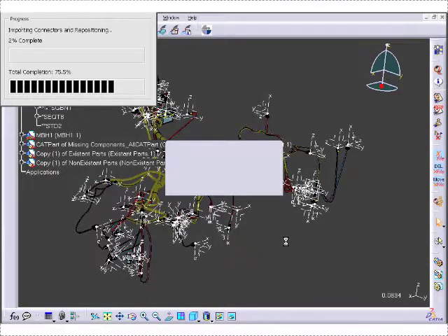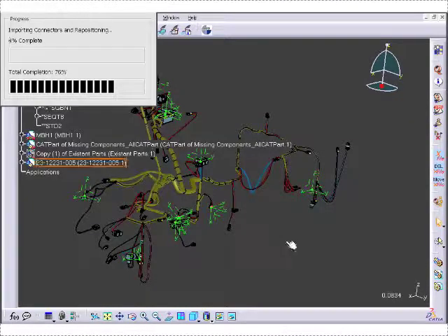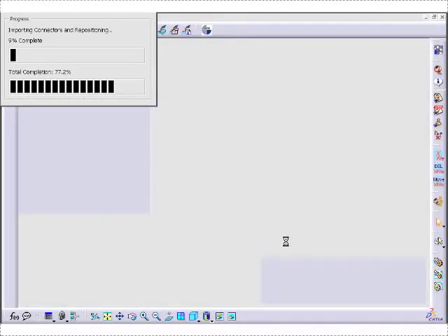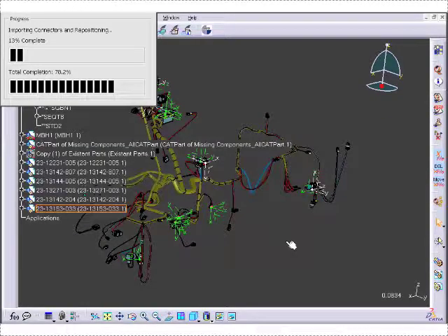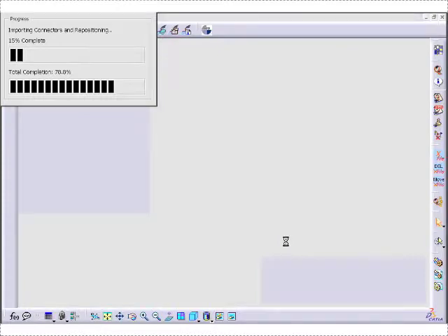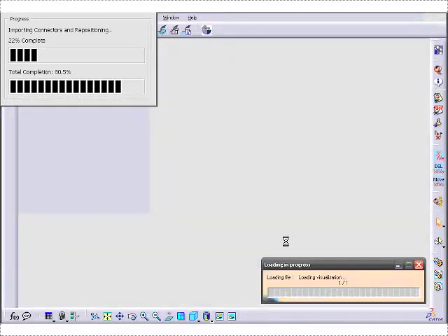And it'll go through and it'll flag parts if there are situations where your company just might not have the same parts cataloged in V5 that you had in V4. It will find those parts, and it will place an axis system into the 3D space in the color of green.